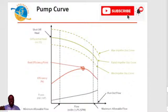Now, that best efficiency point is the flow rate at which the pump has the maximum efficiency. So on the efficiency curve, if you look at the point where you have the maximum efficiency, and you trace it down towards the horizontal axis of the pump curve, whatever flow rate you obtain is the flow rate at which the pump has the maximum efficiency, and that is called the best efficiency point flow rate.